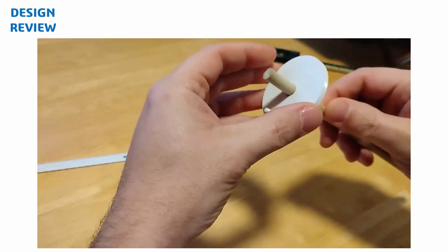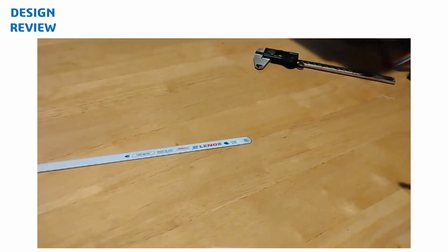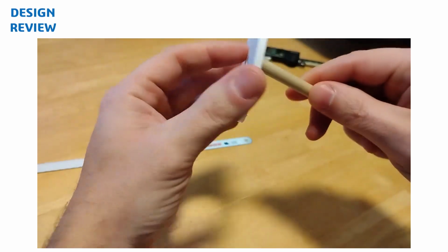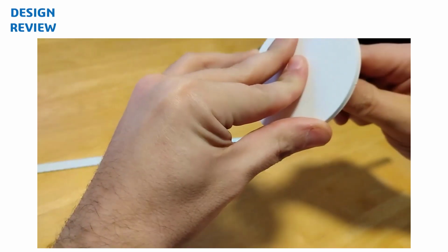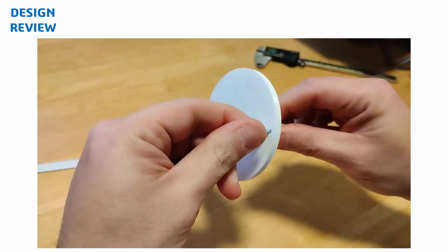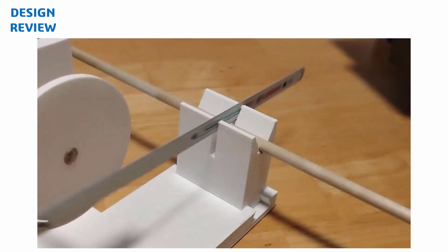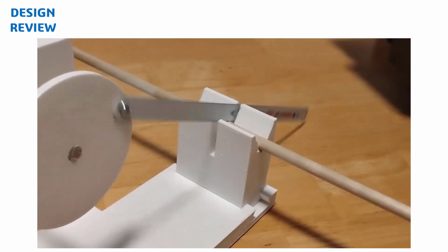Here, we see that the cam does not fit snugly into the dowel and causes the saw to stop cutting. I made the hole for the dowel a bit smaller and made the cam bigger overall. I also made a hole in the cam and used a small screw to reduce friction on the saw blade. Take these as learning opportunities to design different interfaces between components.